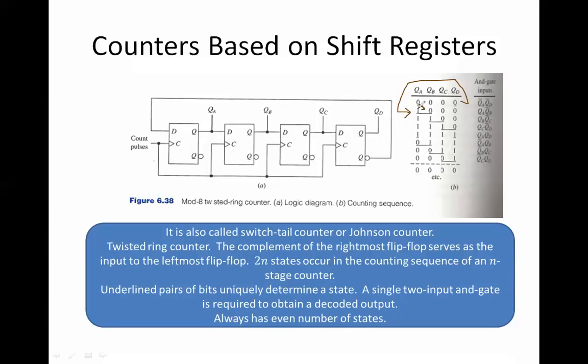So as you can see, it keeps passing by. At one point of time, this 0 here becomes what? It becomes 1 in the next state, because the complement of 0 is what? 1, and this 1 which was here will go this side. So it is just a one bit right circular shift.